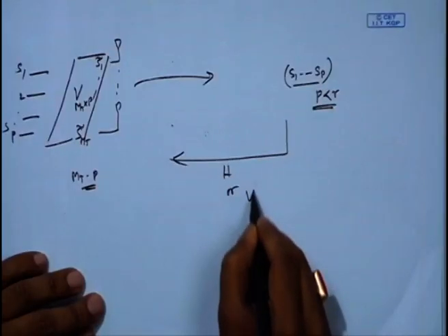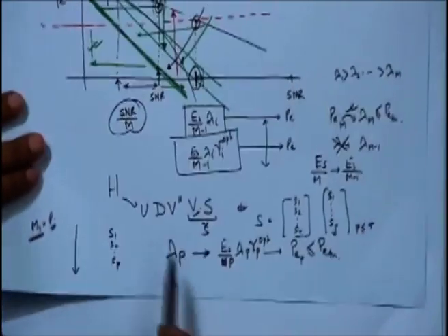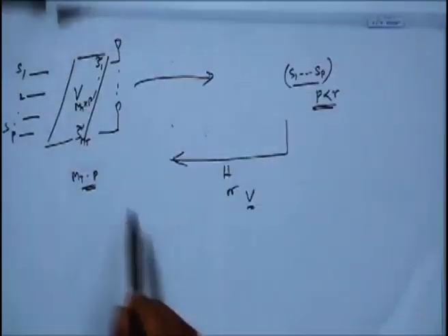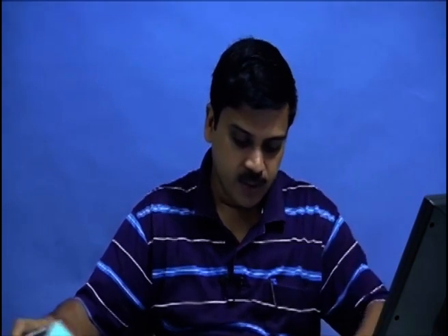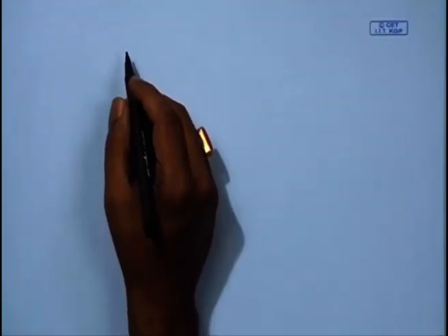So, this particular scheme requires a feedback of either H or of V. That is clear, because we will be encoding with the V matrix at the transmitter. So, we need to talk about schemes where you do not have channel state information at the transmitter, because that would allow use of practical schemes, and that would be much more beneficial than using full channel state information at the transmitter.